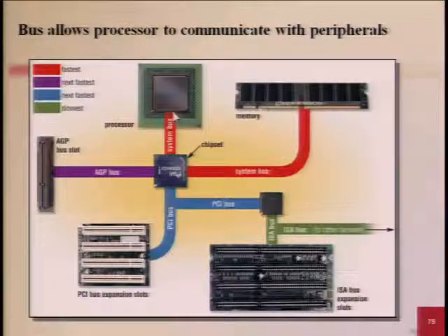The fastest communication is called the system bus. The processor communicates with the memory using the so-called system bus. And there are other buses to connect to, like AGP for the graphics card, okay? And also PCI for all the other high-speed devices and connectors, right? So this is just to show you one. And also sometimes they use another adapter to convert the PCI into ISA.